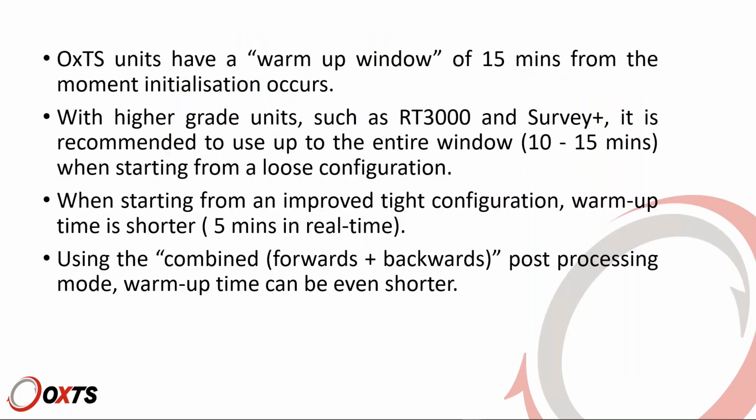The warm-up. The first thing to say is that you have a warm-up window of 15 minutes from the moment initialization occurs. This is not when you switch on the system, this is when you initialize. You've got 15 minutes to complete your warm-up. Higher grade units, such as RT3000, have stronger IMUs, and they need some more time to learn about the surrounding environment. So you can use up to the entire window, I would say at least 10 minutes,